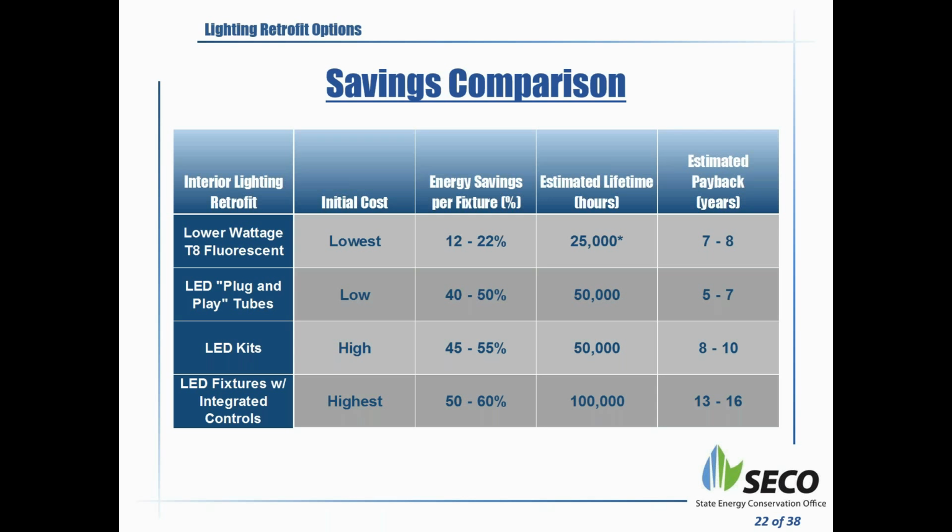So LED plug and play, we have to watch out for the words plug and play. It seems that you just take the old one out and put the new one in, but I'll go over certain scenarios and what to watch out for even when you're considering that simple retrofit. They have relatively low cost, as I mentioned. In 2014, they were not even an option. Around 2015, they started at $20 to $25 a lamp, and now they're down to almost $10, plus or minus, a lamp.